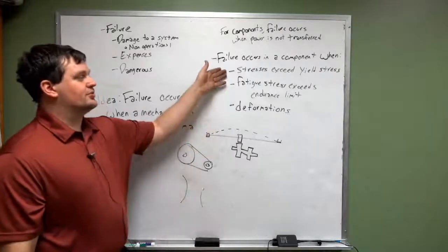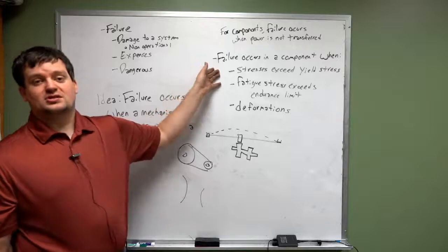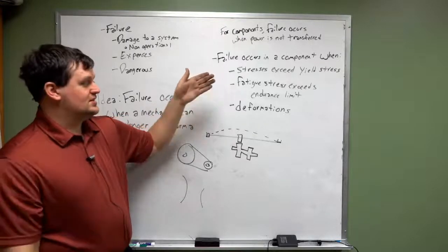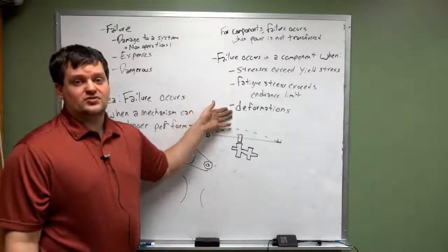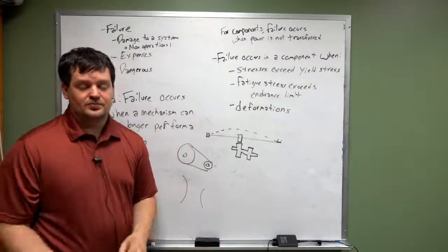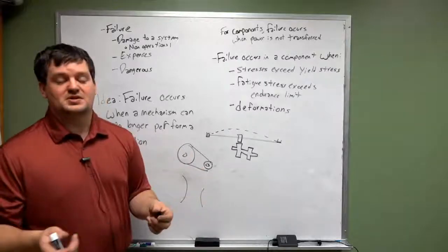You really have to look at all three of these. First of all, whether or not the stresses are low enough that it's going to succeed. Second of all, what kind of fatigue loading is occurring. And third of all, what kind of deformations are occurring in your system as a result of the loading that's being incurred on it.